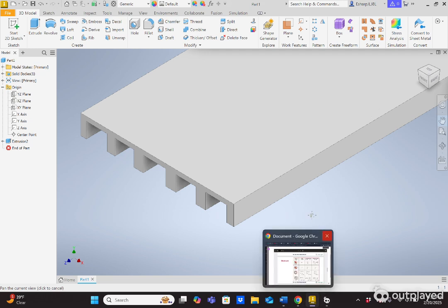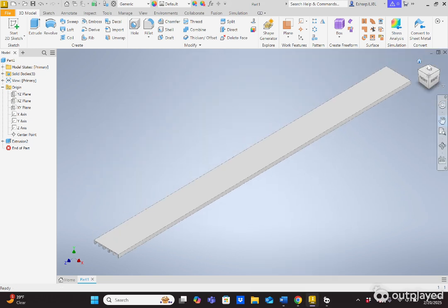So that's kind of all the theory and mathematics around it, right? I really want you guys to understand that as you select a different material, it's going to have an impact on the deflection, but we can control how much it deflects by our design of that cross-sectional area, right? As we change those values, it's going to change our I value, which will in turn change our flexural rigidity as we balance out to get the same deflection value. So let's go ahead and get into the actual stress analysis that I talked about earlier, and I'll show you guys how to do that.